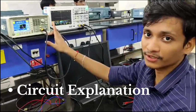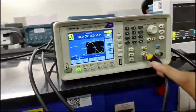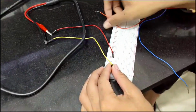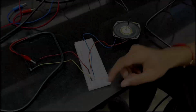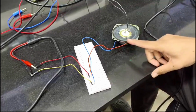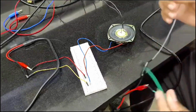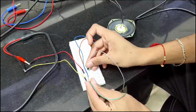Everyone, now we are doing the piezoelectric experiment. From this arbitrary function generator, we are giving a sine wave through this to the breadboard and connecting this to the piezoelectric sensor. By connecting this in this way, we will get the input through this to the piezoelectric sensor. And now to read the input which is coming from the arbitrary function generator, we have to connect this to the oscilloscope.